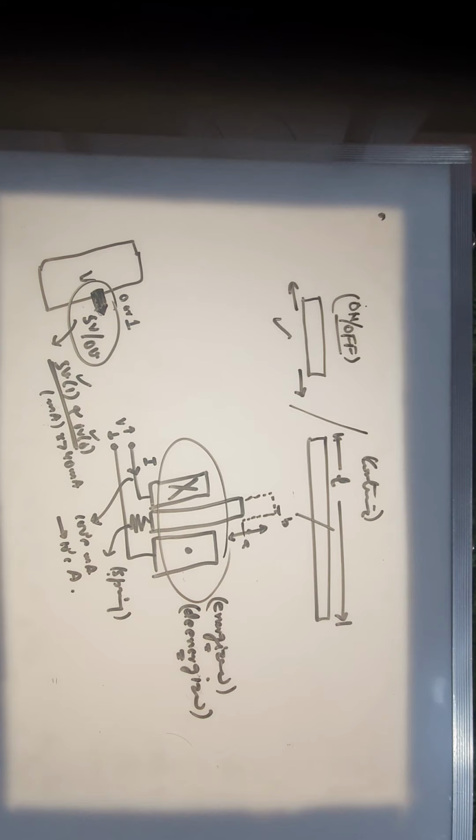So what needs to be done? You need a driver. Driver means a subsystem, an electrical system that can drive your solenoid. That means it will provide it with the requisite amount of current and the requisite voltage so that it will plunge in and out, providing the force or pressure that it has been designed for.